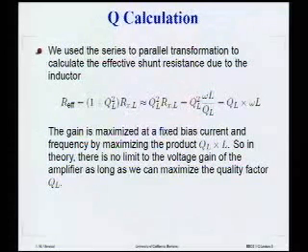Okay, so now we can see where that calculation on the previous page comes from. Remember, I want to calculate R effective. R effective is the effective resistance of the load tank. And in the limit, let's say that I don't use a load resistor, and let's say my capacitor is very good compared to my inductor, the only thing that will limit the quality factor of the tank is the quality factor of the inductor. And so here I take the series resistance of that inductor, which is, let's say, a few ohms, and I transform it to a parallel resistance. And that's roughly Q squared times Rx.